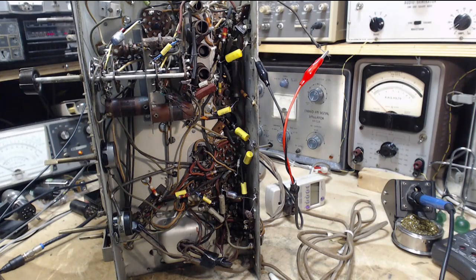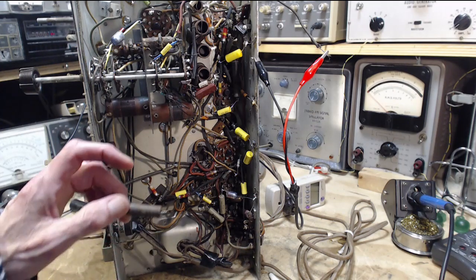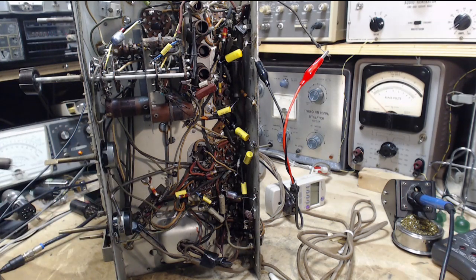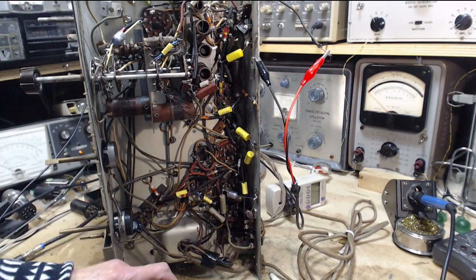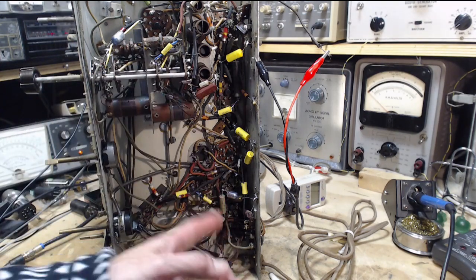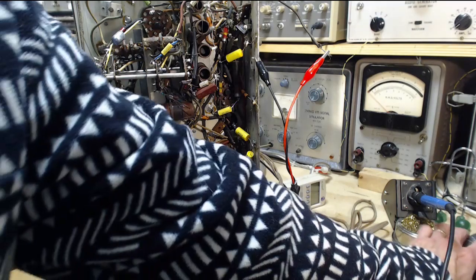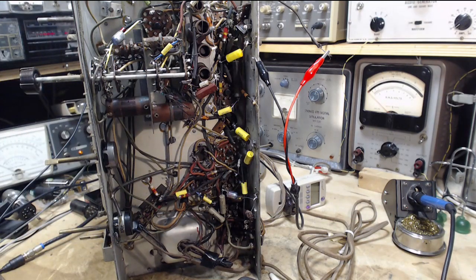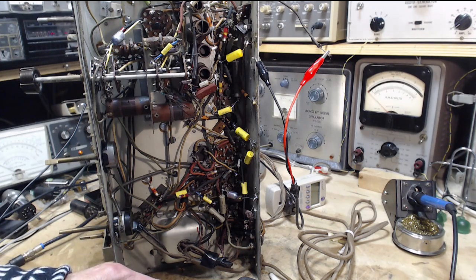And again, what the real capacitance is of this capacitor, I can't really tell. It's enough of a leak in it that the measurement will show high. It will show almost certainly more than 0.2. And I don't believe it. So, okay, we're all set here. Now, I was going to test the resistances of some of these resistors before we turn the set on. Not a particularly good idea to try this with it operating. Okay, wait a minute, that's not right.